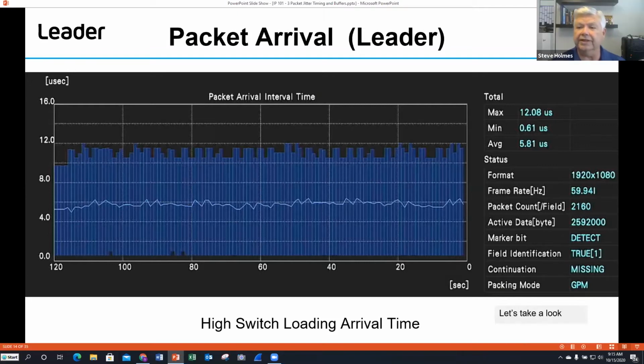Yes, unless someone has done something like oversubscribe a port or oversubscribe an encapsulator. I have seen that several times where people have an encapsulator with SDI feeds coming in, and it can take 6 HD flows, but all of a sudden they take one of the HD flows off and put on a 3 gig flow, and now you're sending out more than 10 gigabits worth of data, and everybody on that encapsulator is now in trouble.